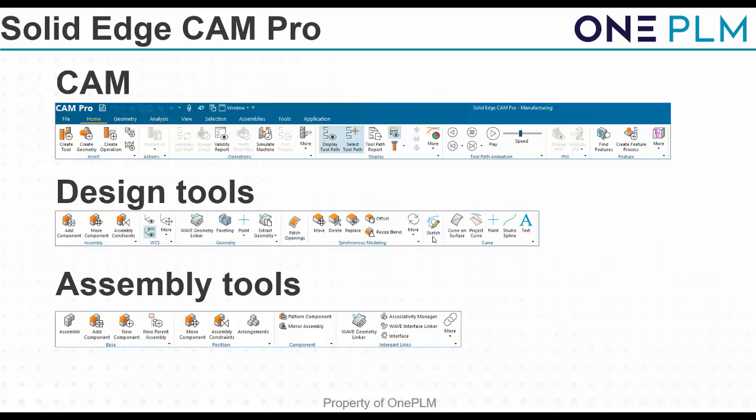This is the full proper sketch tool that you have in NX CAD for all the CAD designers that are doing sketching and extruding models. This is the same sketch tool as you get in CAD. And you can use that wireframe geometry to actually create toolpaths. So the toolpaths inside Solid Edge Cam Pro, you can drive off wireframe geometry, you can drive off the edges, you can drive off the full model, and you can drive off faces of the part as well. So the flexibility is all there.